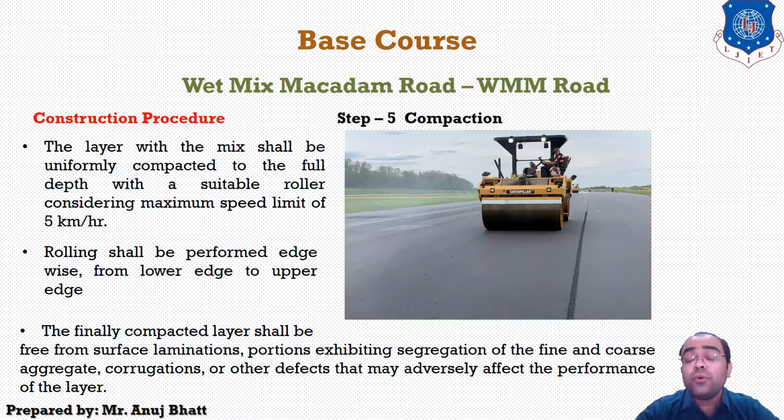While in the portion of the camber, the rolling should begin at the edge with the roller running forward and backward until the edge has been compacted firmly. The roller then progresses gradually towards the center line of the road, uniformly overlapping each preceding track by at least 1/3 width. Such compaction procedure should be continuously done until the pavement is completely compacted.